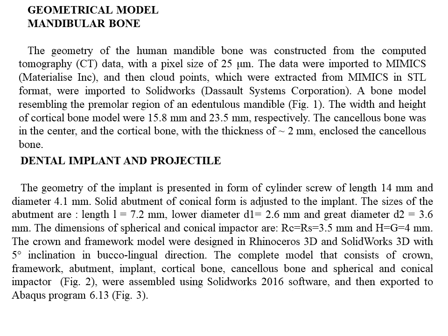Interaction between the bone and implant during simulation of the implantation process is complex and requires definitions of contact conditions. In the present study, contact is defined in Abaqus software using surface-to-surface discretization because it provides stress and pressure results that are more accurate than node-to-surface discretization.